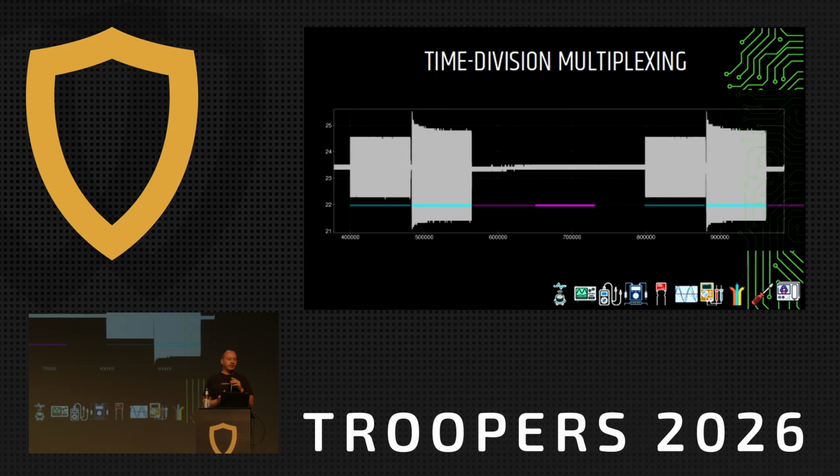Now, looking at the time frames a bit closer, we can see time division multiplexing is really there. So I marked them with blue, with cyan and purple. There are 4 slots. And by the voltage, you can see that the first slot is downward facing, so to the phone. The second slot is upward facing. Why? Because the voltage is higher, and I'm capturing at the phone end, which means that's where the stuff is coming from. That's my assumption here.